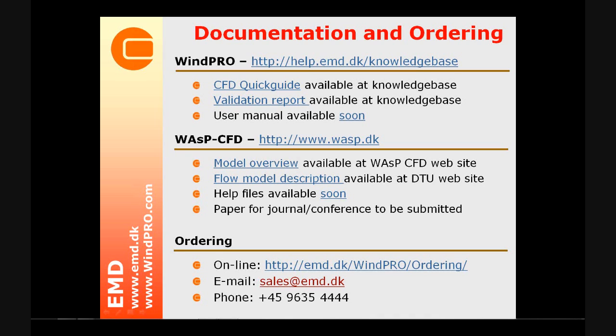So once you've done the CFD calculation, you can actually play with the stability parameters, and you can improve your profile fit. So the answer to this is no. Of course, it's always a very good thing to measure as close to hub height as possible. So I recommend that in general, but these results do not imply that it's mandatory, because we could have gotten better profile fit if we had wanted to adjust the stability parameters for each of these sites specifically.